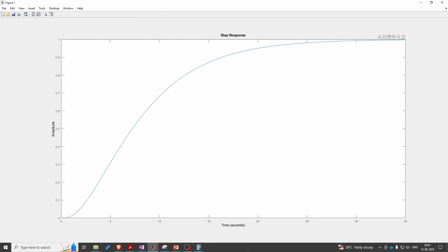So just from the plot you can see that initially the value is close to 0 and then ultimately it starts to rise. So this term we can approximate by this time delay term and then fit the first order process. That is what these approximations do.